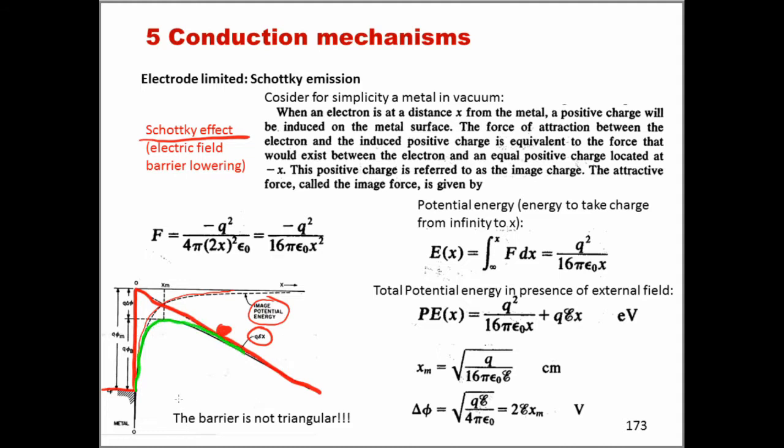This whole Schottky effect is telling us that there is a barrier lowering, represented here by this electrostatic potential delta phi, or this potential energy q delta phi, that is always at play when there is some charge near the metal semiconductor interface.